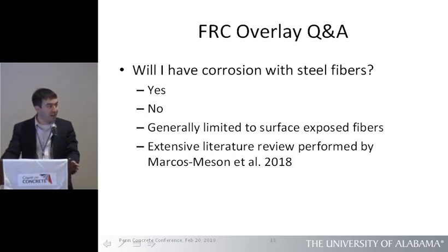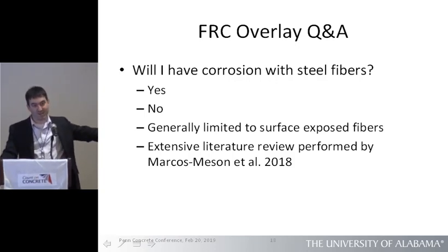Now, if it cracks a lot, yeah, the salts can really go in and start corrosion. But generally, it's only at the surface. If you're really interested in salt corrosion of steel fiber reinforced concrete, you can look up that reference. That reference only deals with steel fibers and corrosion of salt water and de-icing salts.